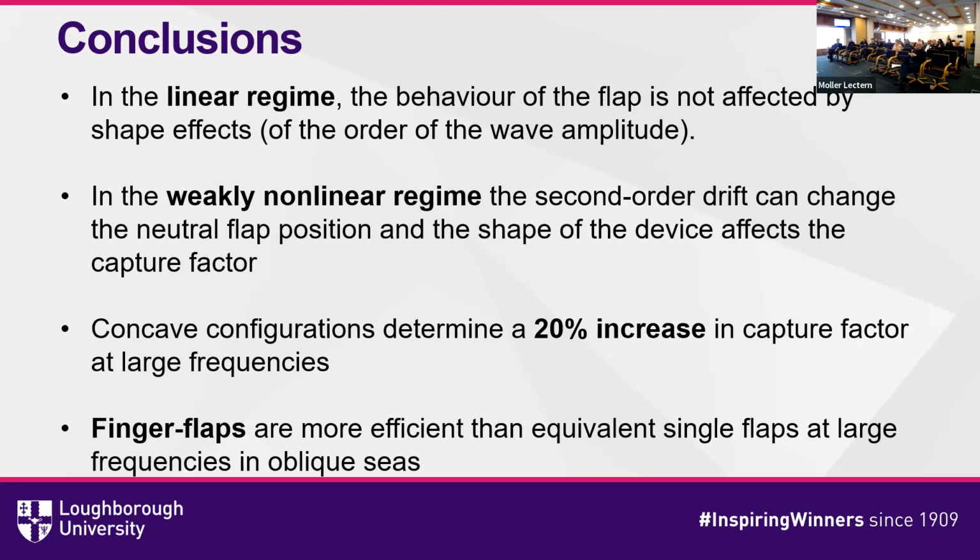In particular, I showed you that engineering or designing the device in a way that it's essentially concave determines a 20% increase of the capture factor at larger frequencies, and that this is only possible in normal incidents with a single flap, but this also becomes possible in oblique incidents with a finger flap. So it looks like using the same width, but cutting the device so that it behaves as an articulated system of devices, can actually increase the power capture in obliques.